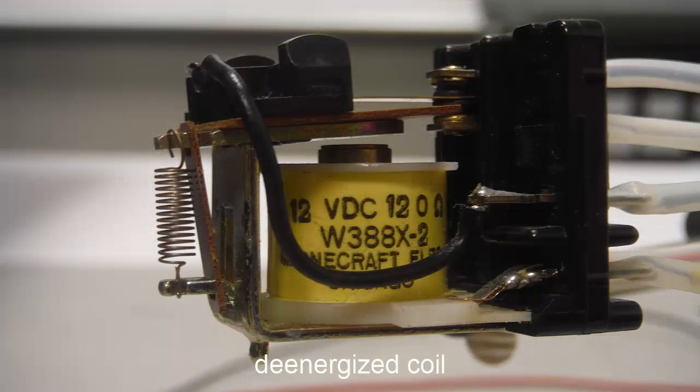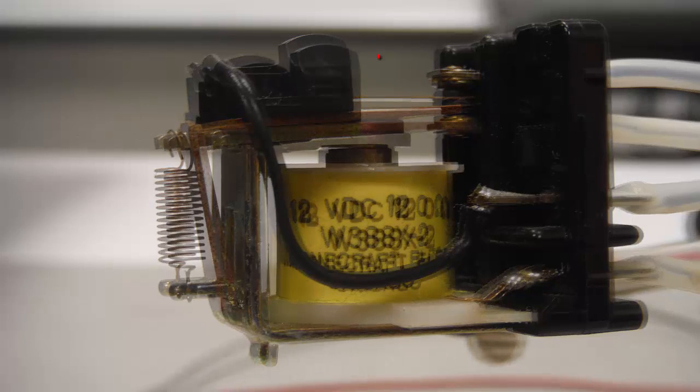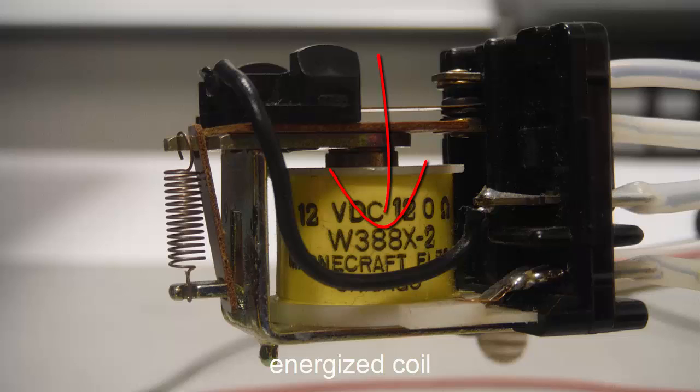The state of the coil inside a relay is the determining factor whether a particular switch is in its deactivated or activated state. The coil is part of another electromechanical device known as a solenoid. A solenoid is an actuator, a term that means a device that takes one form of input and converts it into mechanical movement. In this case, the solenoid converts electrical energy of the control signal to linear mechanical movement via an armature. When the coil is energized by a low voltage control signal, the armature is pulled towards the coil and the contacts attached to the moving armature change from their deactivated to their activated or opposite state.